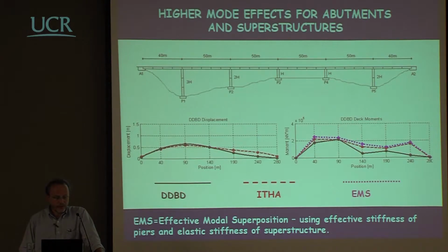So instead of having something like this, you maybe add also some isolation device here and here, and if you look at the displacement shape from the top, as you do in this plot here, the deformed shape of the deck can be similar to a straight line.